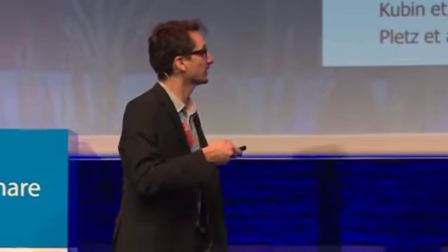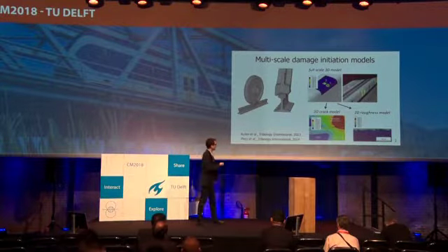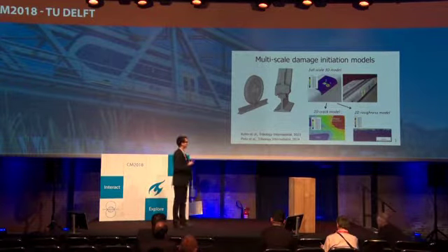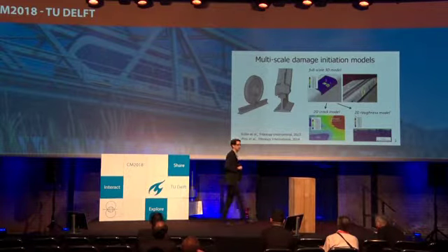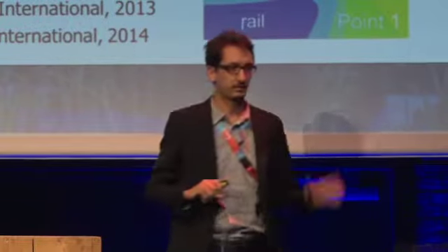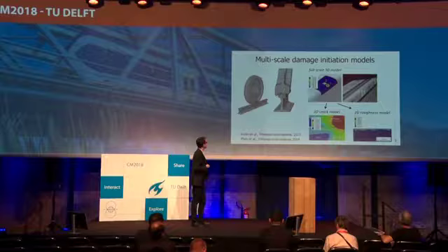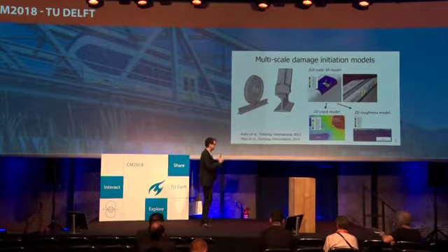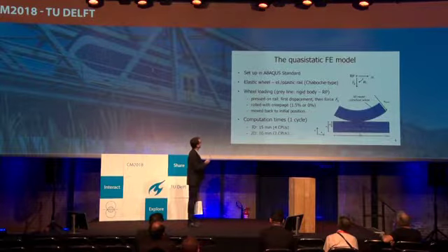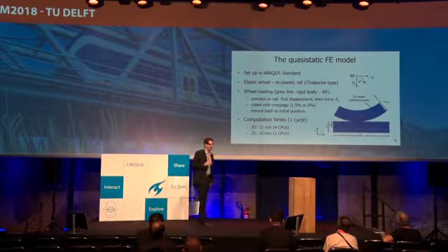And then we went into 2D models, one with a crack, where we tried to investigate what happens to the crack, what differences on that scale, or what parameters on that scale influence the crack driving force. And we also used a roughness model, where we saw that the small asperities and roughnesses influence the upper surface layers, some micrometers. The plastic deformation is highly influenced by this roughness. And basically, we thought about how to transfer loads from 3D to 2D. 2D is really good because you can use roughness and cracks very efficiently. Well, one thing there was we just showed how it could be done, but we didn't really show how it was feasibly done. So now I introduce a quasi-static finite element model where we do something like that, but it's a little bit more basic.